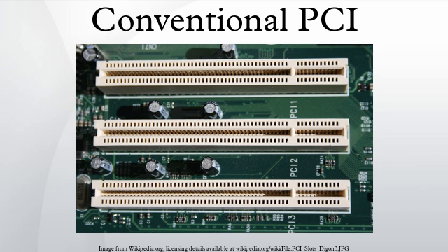Signals nominally change on the falling edge of the clock, giving each PCI device approximately half a clock cycle to decide how to respond to the signals it observed on the rising edge, and half a clock cycle to transmit its response to the other device.